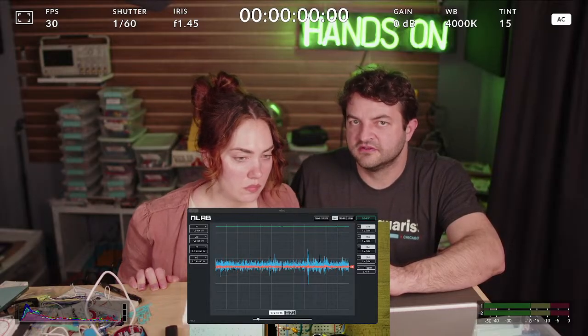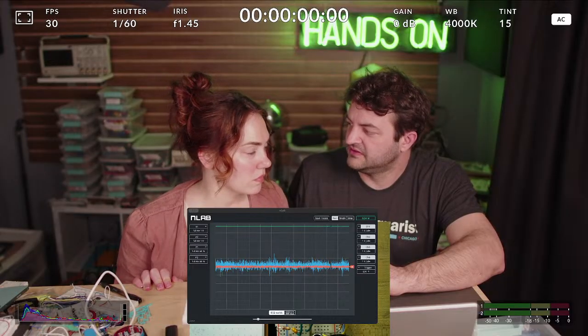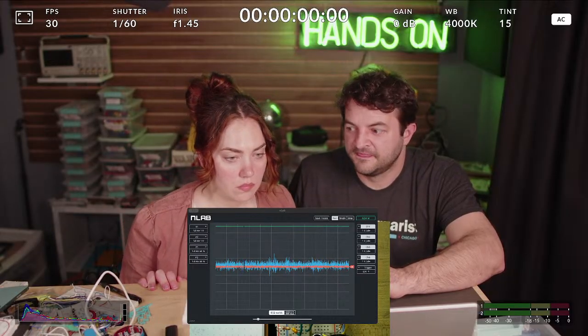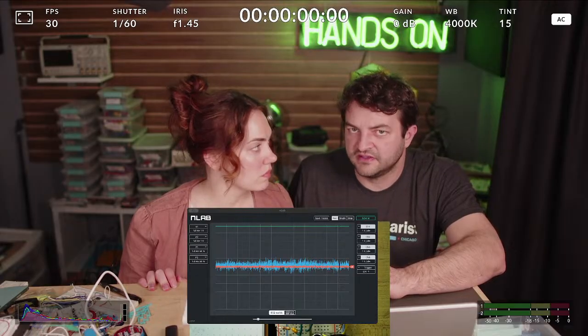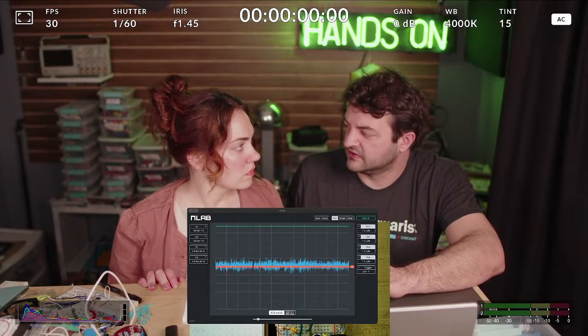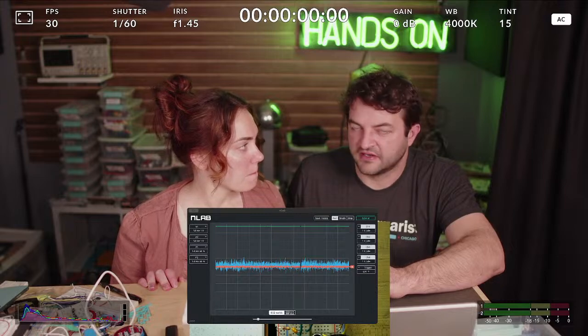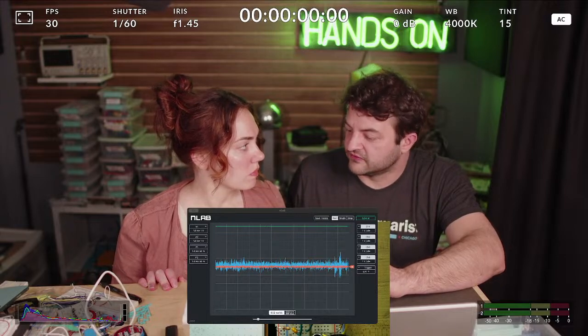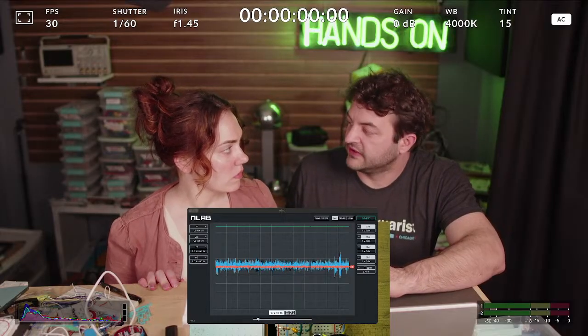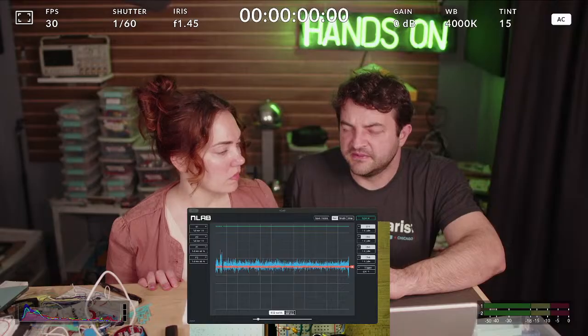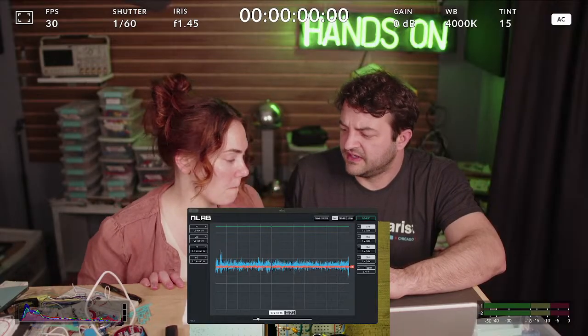If it's over 10 microfarads, it's probably aluminum. We used to use tantalum for the middle range, like 0.1 to 10 microfarads, but those aren't as popular anymore because tantalum's a conflict material. So instead, the ceramic ones are now anything from 1 picofarad up to 10 microfarads. And then the film type, I think, might have different temperature ratings.